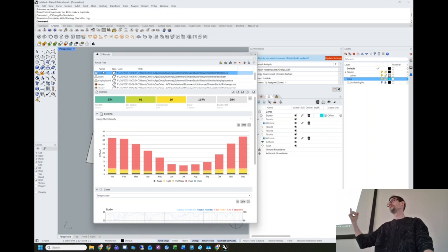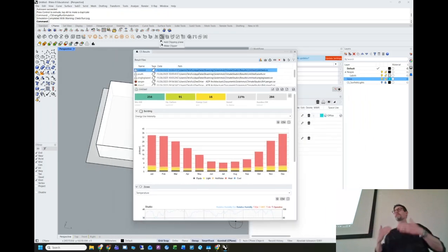Why has that happened? Any idea? Have you been in winter? You sit next to a window with the sun coming in. Feels nice and warm, doesn't it? Lovely, cozy. The sun's coming in. What you're getting then in the winter is solar gain. You're getting the heat effect of the sun coming in and warming the building. And so what happens when you move a south-facing window onto the north face is you lose out on that solar gain, and all of my heating bills in the winter have gone up.